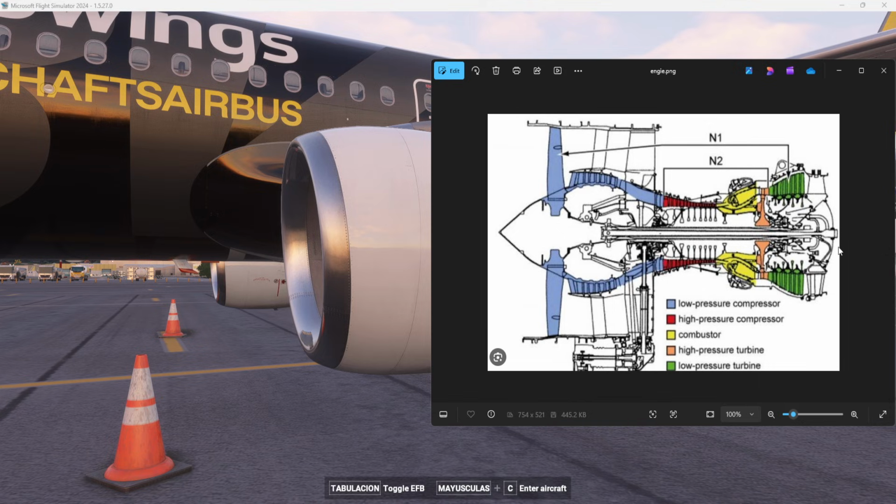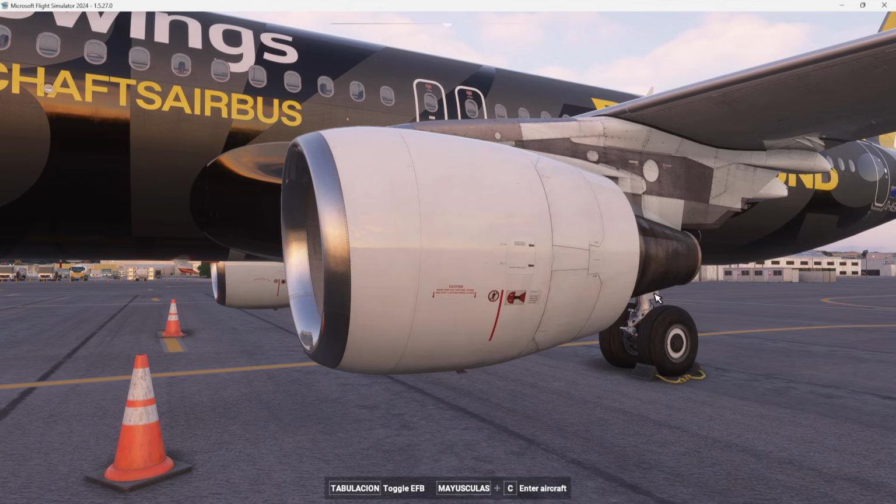After the low pressure turbine, the hot gas has lost almost all its energy, so it is not moving at higher speed. So we can produce some residual thrust, but the 80% goes by the bypass. It does not pass from there. So we have the core of the engine, where 20% of the air passes in order to produce energy for the engine.